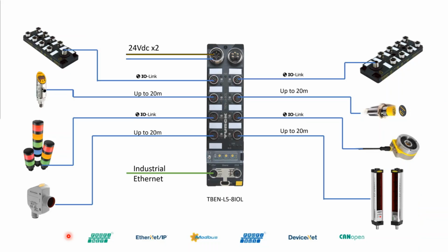All right, I like this slide because it shows the different types of things you can do with IO-Link that used to be different IO cards or different modules. So with this application, I've got some discrete IO and I've got some analog IO. Historically, out in the field, and I'm using the camera now, we might have to do 2 of these blocks.